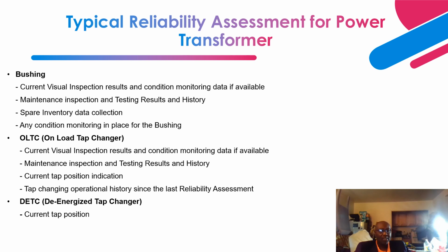The C1 area is from the conductor of the transformer to an electrode that is internal to the bushing, and the C2 area is from that electrode to the tap point of the bushing.